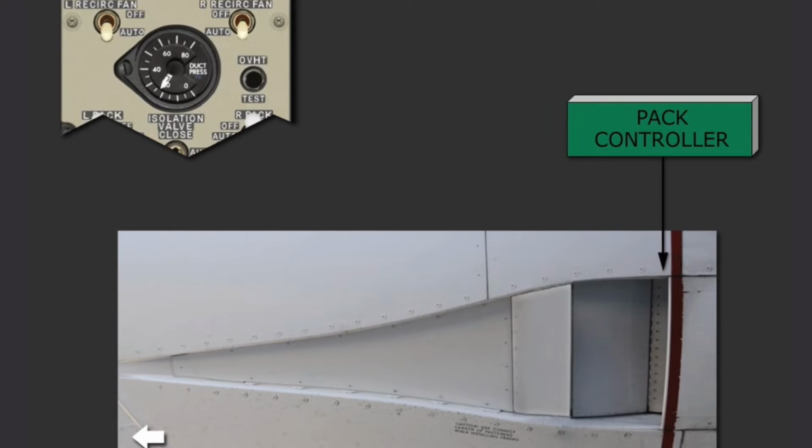During normal cruise flight, the ram air doors modulate between open and closed. This movement is automatic. There are no cockpit controls or position indicators other than the ram door full open lights. To prevent slush and debris ingestion prior to liftoff and after touchdown, deflector doors are installed forward of the ram air inlet. The deflector doors extend automatically while on the ground only and are controlled by the air-ground safety sensor.